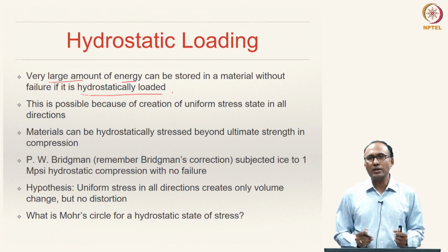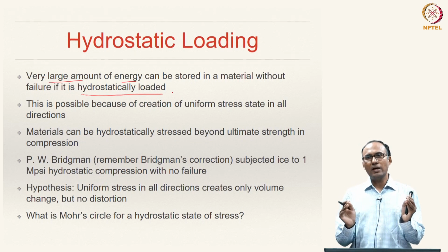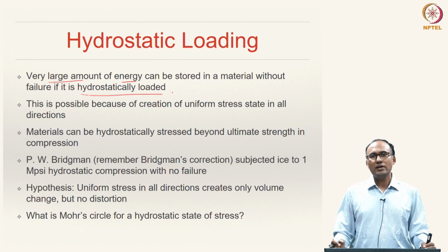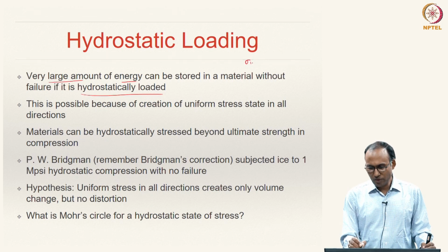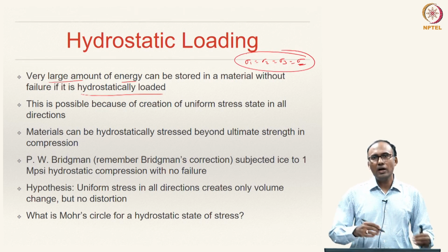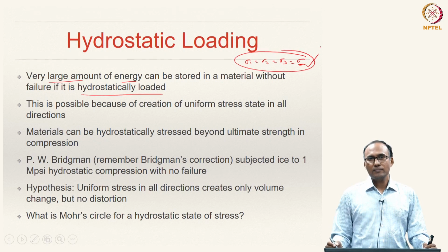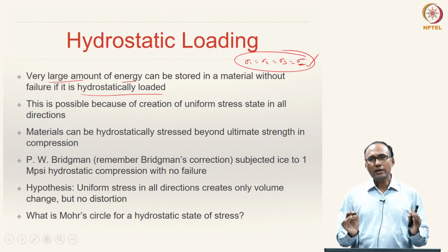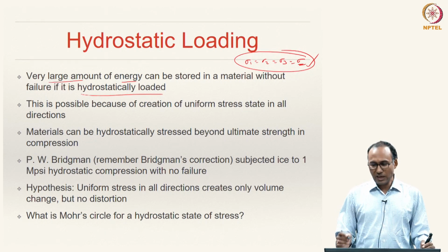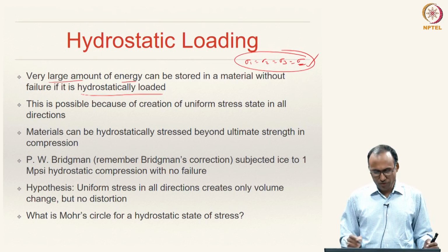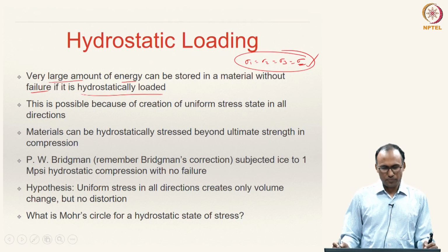What do you mean by hydrostatic loading? Applying a hydrostatic state of stress means having the normal stress in all the 3 directions being equal, right. Sigma 1, sigma 2, sigma 3: if sigma 1 equal to sigma 2 equal to sigma 3 is equal to some constant sigma, then such a state of stress is called hydrostatic state of loading, right. So, if you have this kind of loading, then the material can be loaded without actually having to plastically deform. That means you can store a large amount of energy without failure.